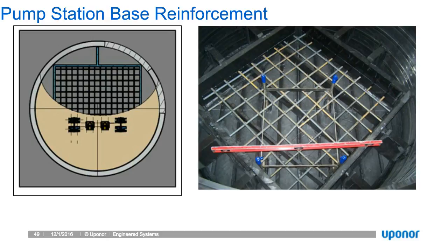So what we do is we actually will encapsulate a rebar reinforced concrete base into the system. We'll drop our anchor bolts in to support the breakaway fittings, and we'll ship the system out to the job site with a cast-in-place, fully HDPE encapsulated base that will resist the vibratory loads of the pump and ensure the system will last 100 years that we want it to.